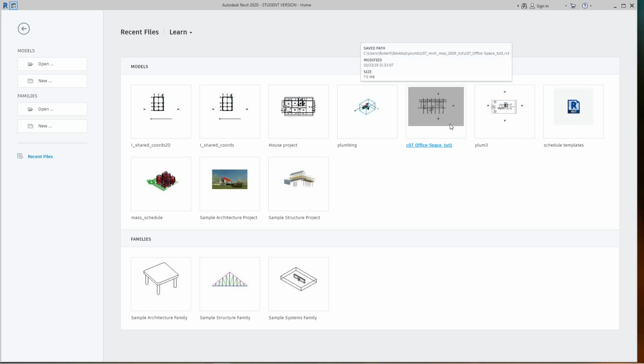Although they might not be visible in all views because of visibility settings and view clippings, the project base point cannot be deleted. This project base point defines the origin (0,0,0) of the project coordinate system. It also can be useful in positioning the building on the site and for locating design elements of the building during construction. Spot coordinates that reference the project coordinate system are displayed relative to this point.